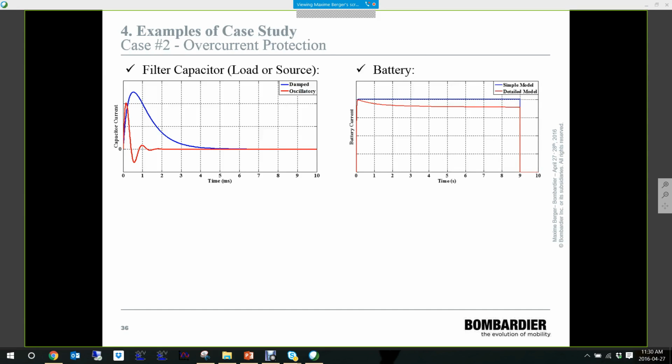Also here, we need to consider detailed battery models, because when we are studying long fault duration, the decrease of the current is non-negligible, so we have to consider that. So we cannot consider batteries as a simple constant voltage source behind its constant internal resistance.